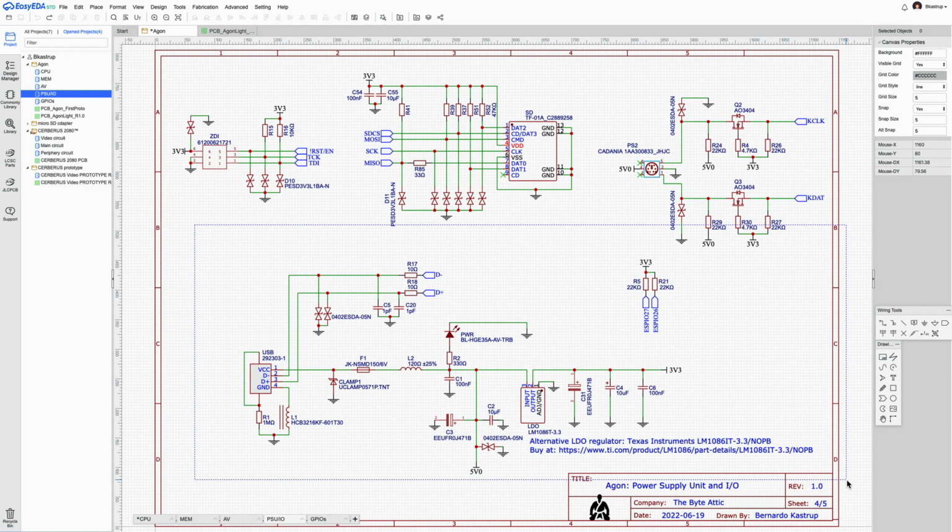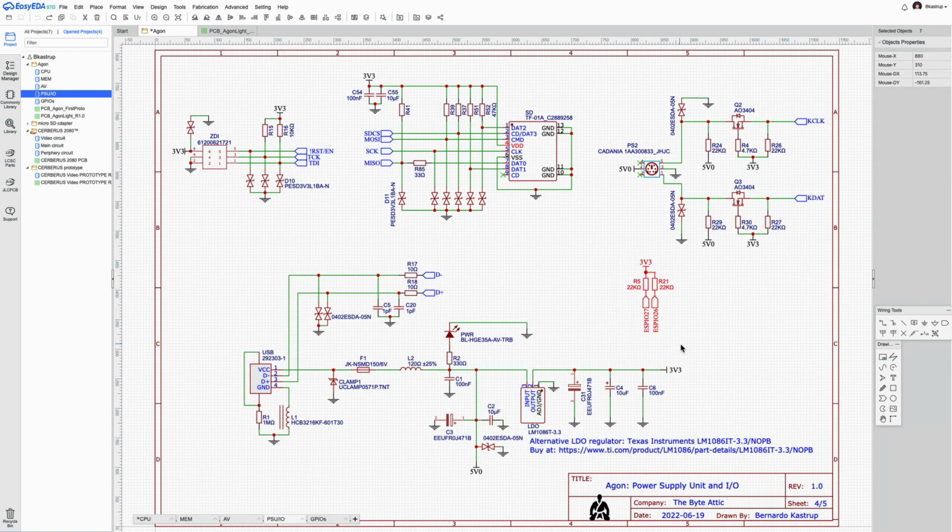Now that's the power supply unit here below. Extremely simple. Well, not including these two guys. These two guys are separate. It's a very simple power supply. It gets 5 volts from the USB connector, that's VCC here. Then the two data lines, the differential pair of USB, are D minus and D plus. They are the ones that go to the USB bridge.